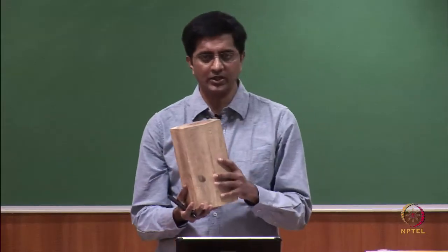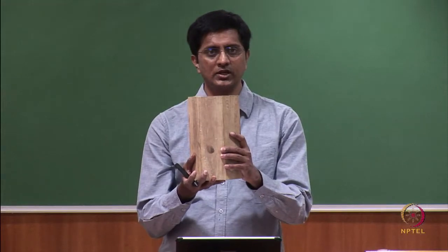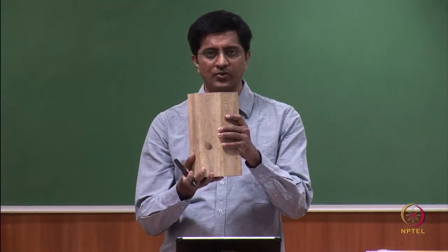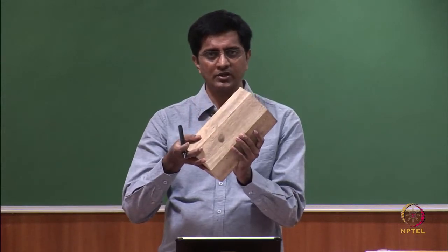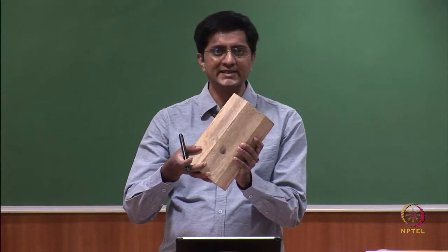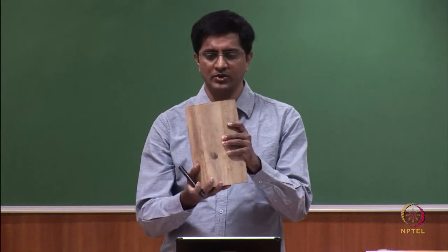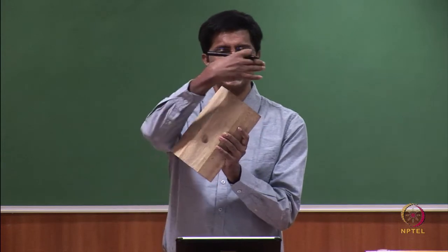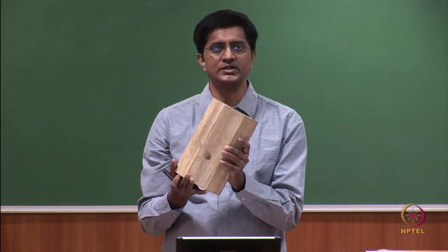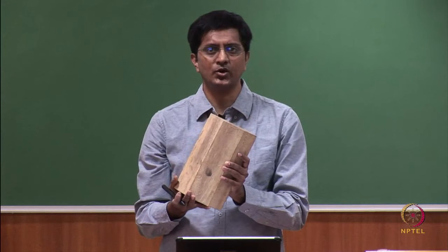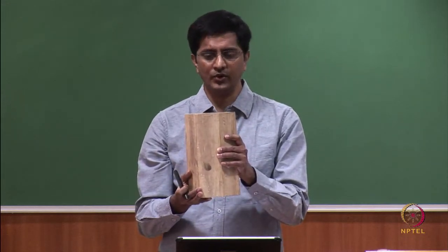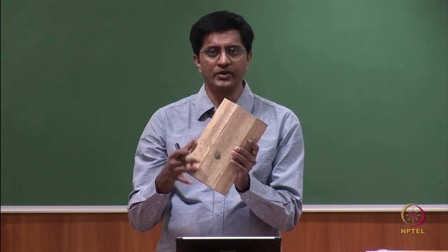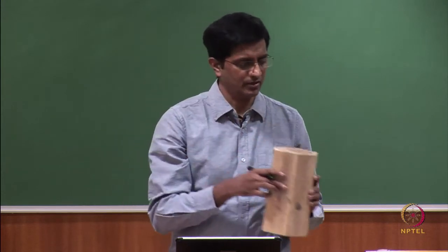So, again I am bringing the object. So, this is the step 1 and this is step 2. So, from step 1 before rotation to after rotation, will the front view remain the same or the top view remain the same? We see that this hexagon in the top view now becomes a squeezed hexagon. It is not the same, it does not retain the true shape, but the front view before and after rotation retains the same shape. The only difference is the shape is rotated.